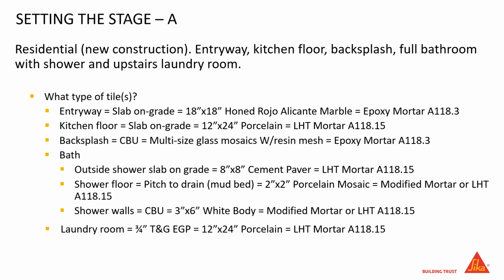So we know an epoxy mortar is going to stick to that. We know for the water sensitivity of that particular marble, we're not going to have any issues. So we're using an epoxy mortar. So we've decided on that. Kitchen floor, slab on grade, 12 by 24 porcelain. So we've got a membrane down. We've got our crack isolation membrane down after we've brought the floor up to tolerances. And we're using an LHT mortar, 118.15.